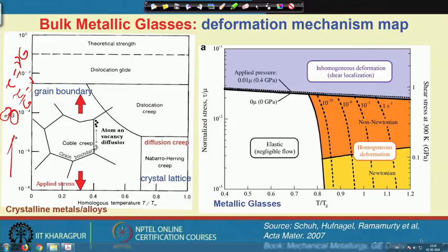So, it basically somewhat represents a critical strain, and the strain is somewhat linked with the mechanics of deformation in crystal. So, similarly here also this tau by mu gives the same type of relation, that is the shear stress by G. So, instead of calling it a normalized stress, we can also call it something like it is equivalent to some sort of critical strain in the material.